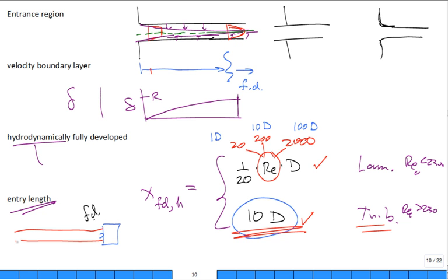Now, do you think that's out there in practice? No. And so if you're a young engineer, a new engineer, you start looking for that. Keep that in the back of your mind when you're walking around plants or looking at designs on paper. And say, okay, we have a flow meter right here. We want accurate measurement of this. What's upstream of it? Actually, you also have to worry a little bit about what's downstream of it too, but primarily upstream.